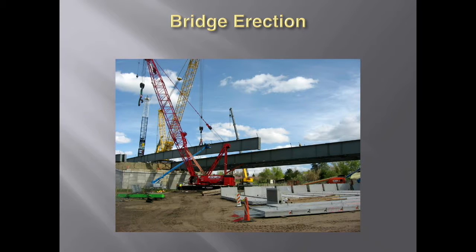In that procedure, it'll tell you locations of the cranes, how they're going to secure the girders before they set them, and any overhead obstacles they have to deal with, wiring, anything like that. The big thing to remember here is not to get underneath the girders. Stay out of the way.